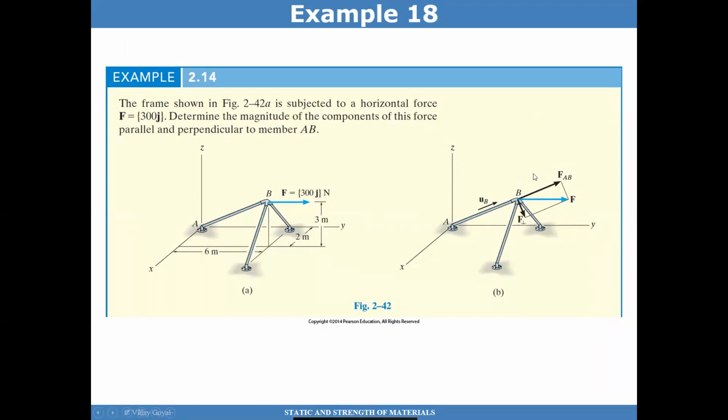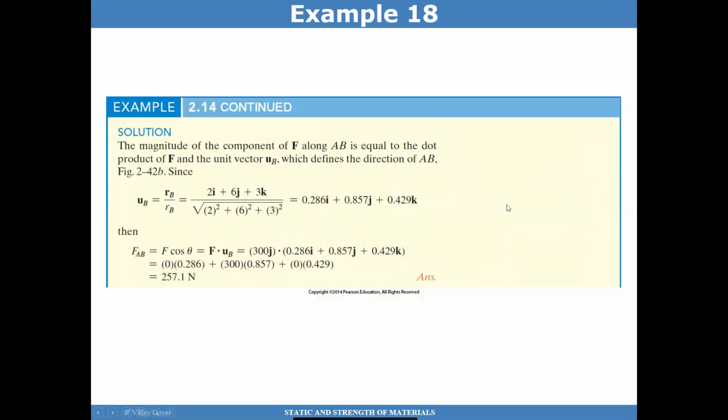And so that's the question. It's very useful to draw it. So this force F, I want to know what is FAB and perpendicular to it. That's really what I want. The strategy is going to be to find this vector, the one that connects A to B, find the unit vector along that, and perhaps I can go somewhere from there.